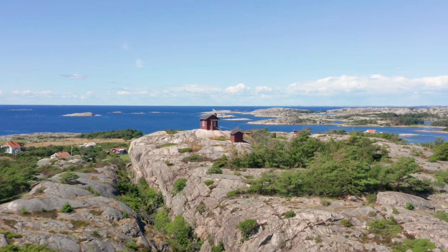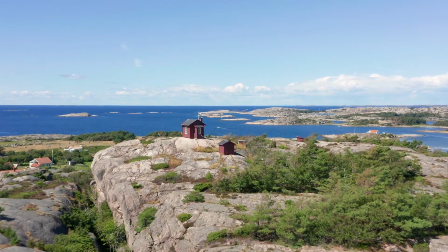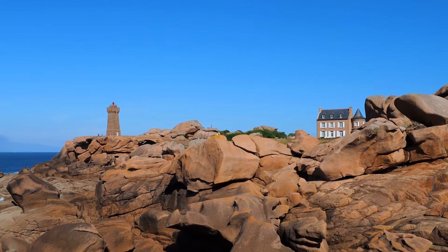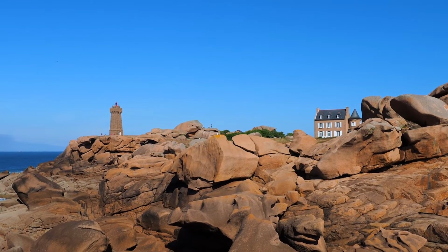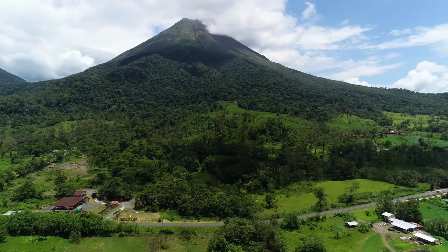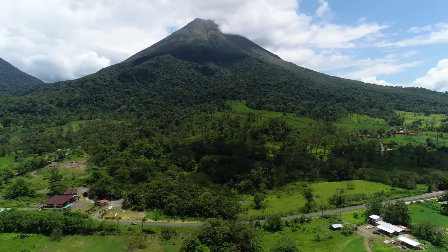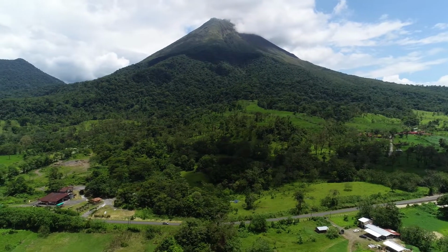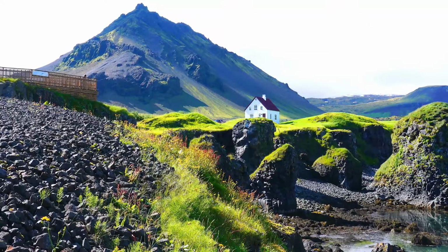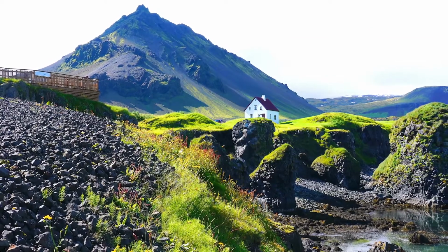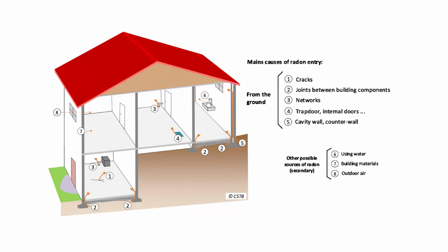Radon comes from the radioactive decay of radium naturally present in the soil and rocks of the Earth's crust, mainly in granitic and volcanic ground. It is a colorless, odorless radioactive gas that is ubiquitous at widely varying levels on the Earth's surface. It is rapidly diluted in the free atmosphere. On the other hand, it enters buildings through leaks at the interface with the underlying soil and may be found in higher concentrations inside buildings than outside due to the confining effect of the indoor space.